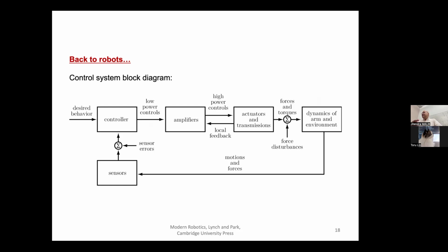Okay. And then there is a higher level controller which is deciding what are the right joint angles to strive towards. So that low level controller often has to work very fast. It's typically operating at 1000 hertz. Whereas your high level controller might be some transformer or neural network which is operating at 20 hertz. So the lower level controllers are always much faster. Okay. Does that make sense? Yeah.